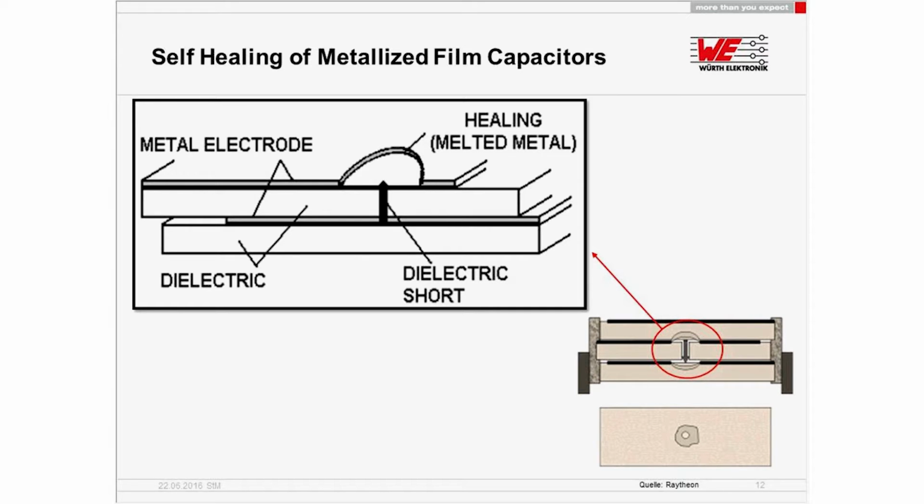One issue you get over time is if you have such self-healing often, for example, for an X2 capacitor, if you would again and again apply high pulses, this means that the capacitor loses capacitance over time. It is pretty tricky to define how fast and how much capacitance is lost, because this phenomenon can be increased and can be very bad if humidity creeps into a capacitor box, because if the resistance is lowered, this effect can start, but it can happen that it burns off way bigger areas than with a dry coil.